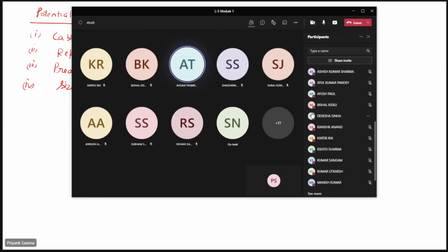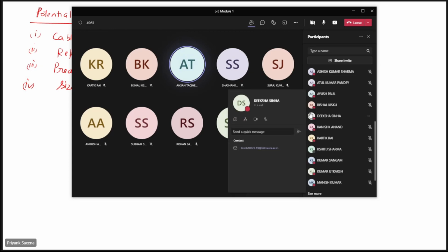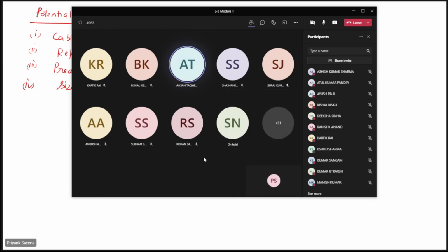So data that is transmitted comes at different times, so the received data is distorted. Delay distortion is basically caused because the velocity of propagation of a signal through a guided medium varies with frequency, right?